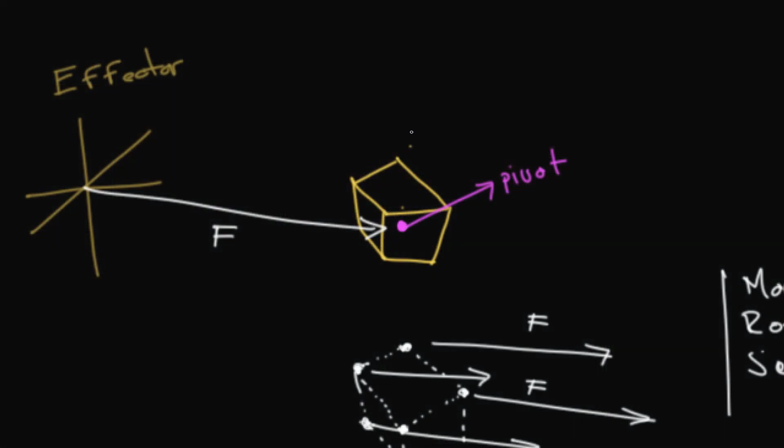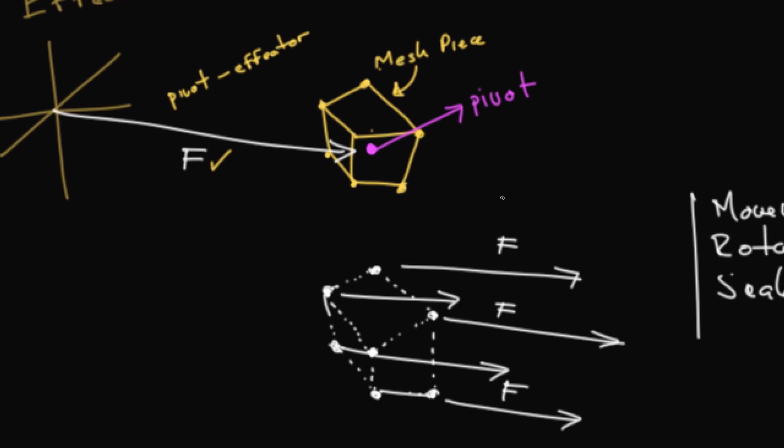Now, this drawing represents the pieces of the mesh and the vertices that compose it. This vector is the subtraction of the pivot point minus the position of the effector. I use this vector to apply a displacement to each of the vertices. In this way, I obtain a uniform and group movement of the vertices with respect to their pivot, which is defined in the two UV maps.